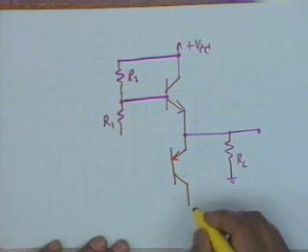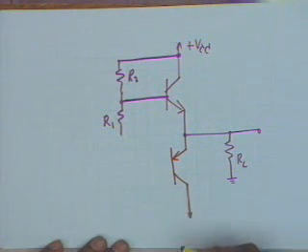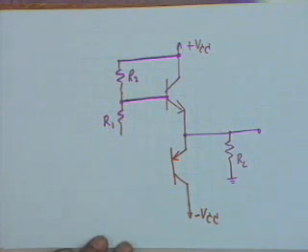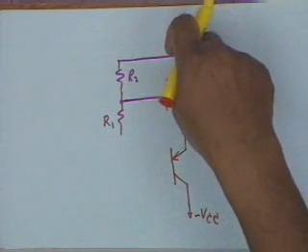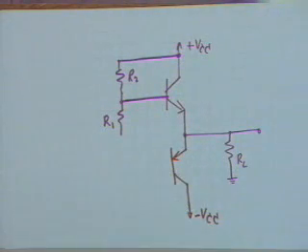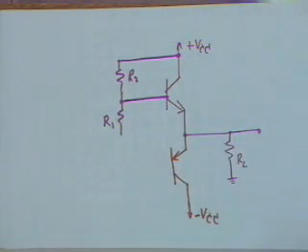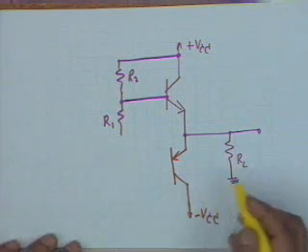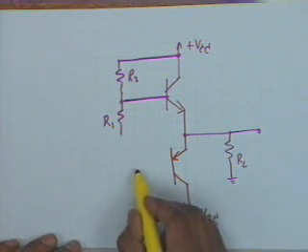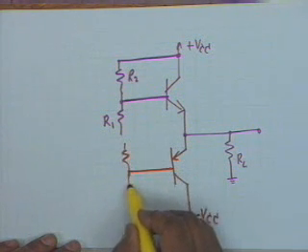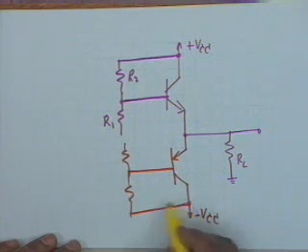And to what kind of a supply should this go? Obviously to a negative supply, so minus VCC. You could have a single supply, this is the positive terminal and this is the negative terminal, or you could have two supplies, alright. There are supplies available, plus 12, 0, minus 12, alright. So this is the condition, and then the usual biasing circuit. The biasing circuit is again the same, R1, R2.